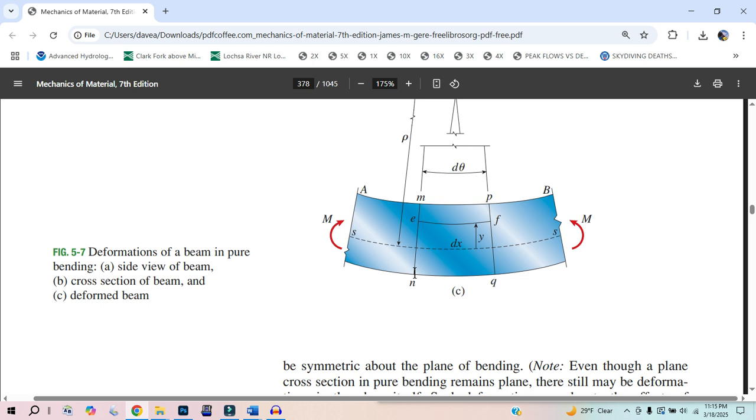So you're going to have a 0.2% increase. If this segment is 1 meter, which is 1,000 millimeters, and this lengthens to 1,002 millimeters, well, that's as much linear elasticity as you got, and after that you permanently bent it, and maybe people died going across this bridge or something. Anyway,